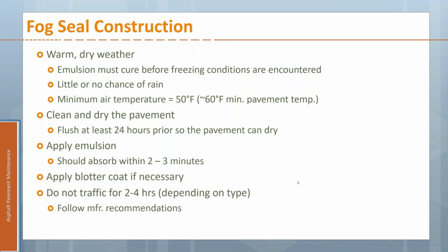The other thing is that the weather will affect how fast that cures out. So if it's a sunny day, warm, hot weather, and you're out in the open, it's going to cure out a little bit faster than if it's a cool day and you've got a lot of shade or it's cloudy. It may take a little bit longer to cure. And since there are so many different types and materials, your manufacturers will be able to help you with exactly how that ought to work.